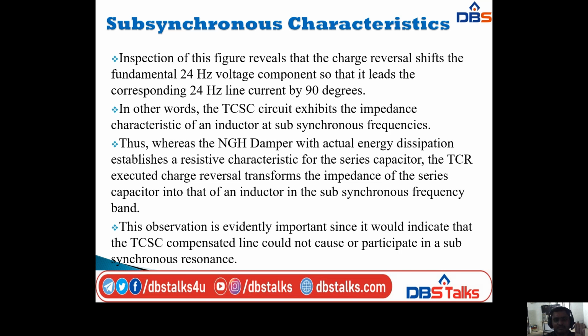Okay, so next, inspection of this figure reveals that the charge reversal shifts the fundamental 24 Hz voltage component so that it leads the corresponding 24 Hz line current by 90 degrees. So in other words, the TCSC circuit exhibits the impedance characteristic of an inductor at subsynchronous frequencies. Whereas the NGH damper with actual energy dissipation establishes charge reversal transforms for the series capacitor, the TCR executed charge reversal transforms the impedance of the series capacitor into that of an inductor in the subsynchronous frequency band.